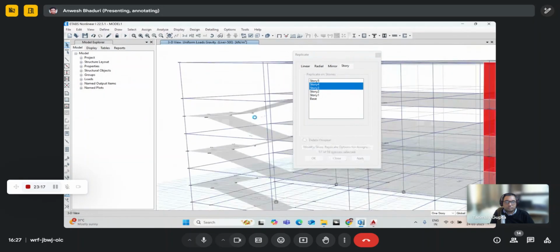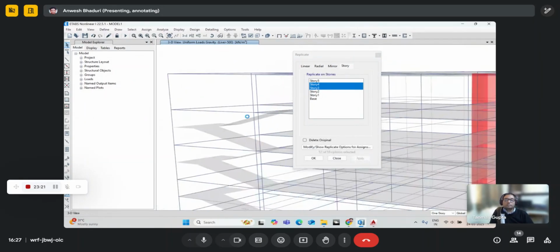We see that the staircases have been created, and we need another staircase over here to the roof. So we'll make use of get previous selection, and you can notice that when the cursor is placed on the command buttons, their respective shortcuts are also denoted.